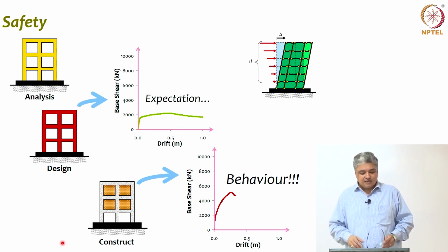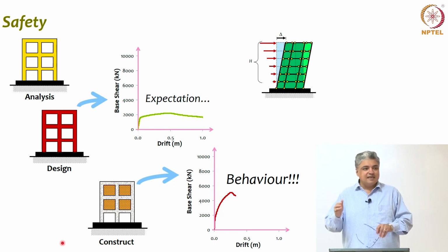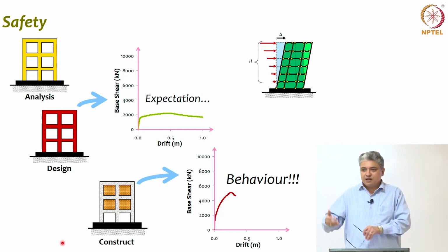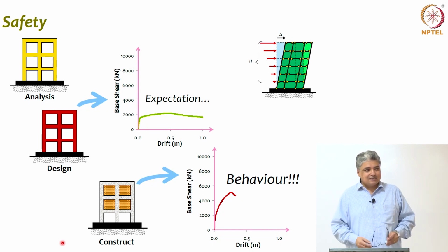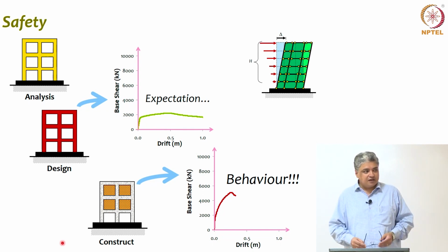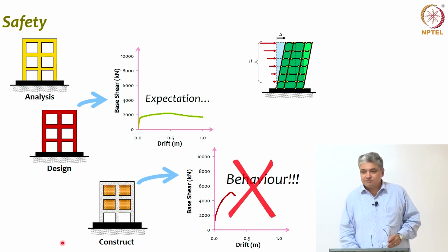But suddenly when we construct, we put these infill walls, the brick walls. So what it does to the structure is, it changes the structure and it changes its behavior. So what you expect while you analyze and design the structure is not what you get after the structure is constructed, and that is not acceptable.